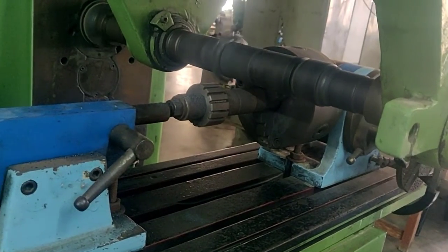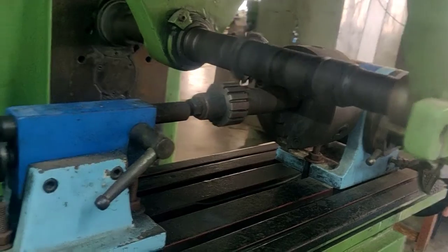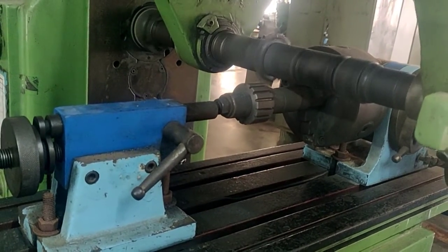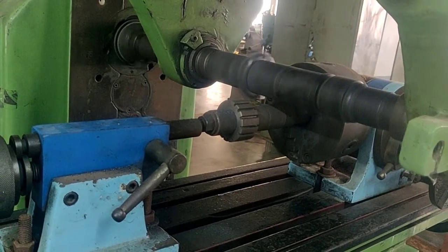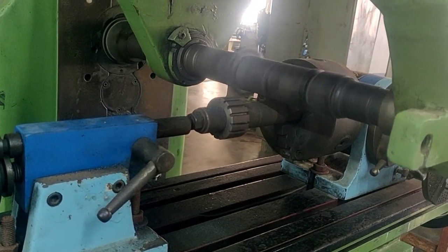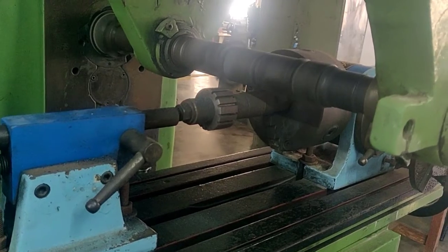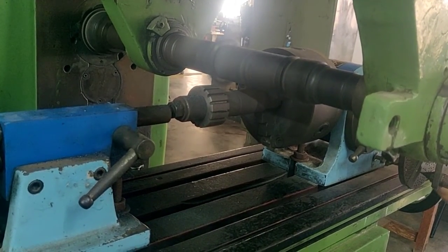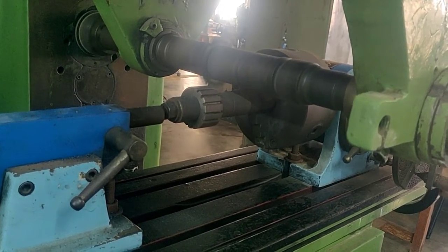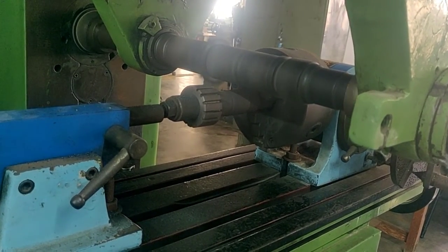You can see the gear cutter, which may be either cylindrical type or end mill type. The cutter profile fits exactly with the tooth space of the gear. With the help of this gear cutting, equally spaced gear teeth are cut on the gear blank by holding the work on the universal dividing head and then indexing it.